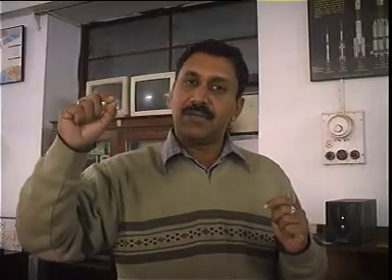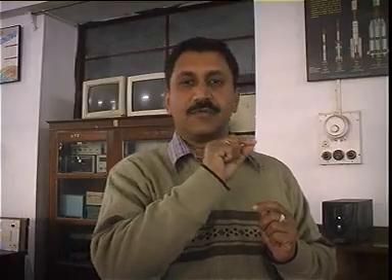Each time I will feed in a signal with a particular amplitude and particular frequency, and I will measure the same signal at the output of the filter, note its amplitude. I will keep on repeating this for every frequency, I will keep noting the output, and I will make a tabular column of input frequency and amplitude at the output. So then I plot a graph between the amplitude ratio, amplitude output divided by amplitude input, versus the frequency. And then I will have a plot which gives me the frequency response of the filter. That's the traditional way we do the filter characteristics.